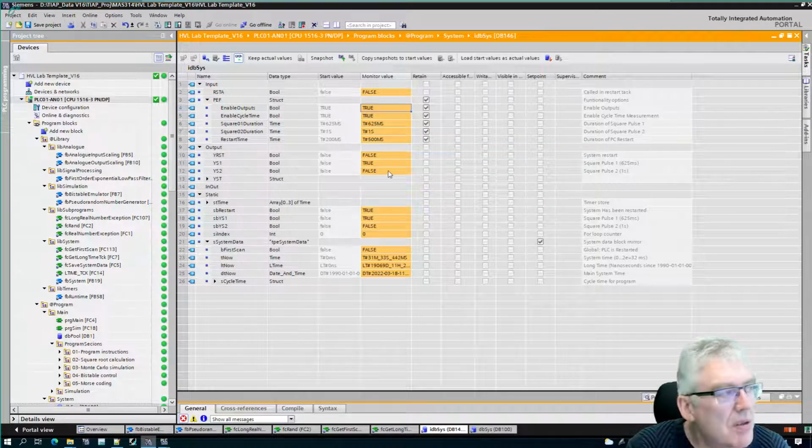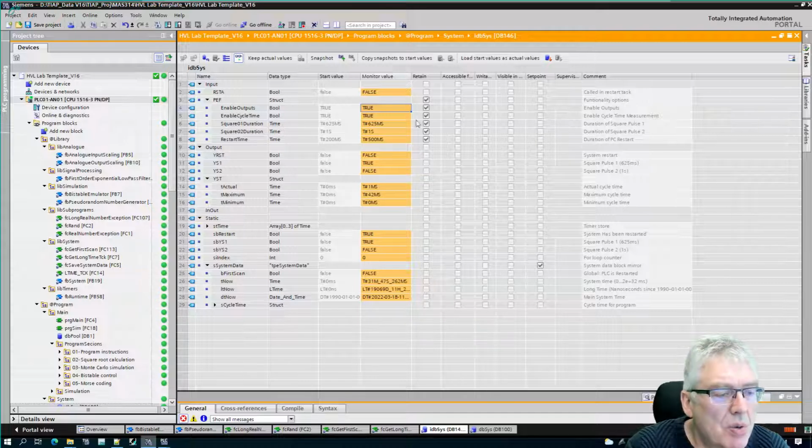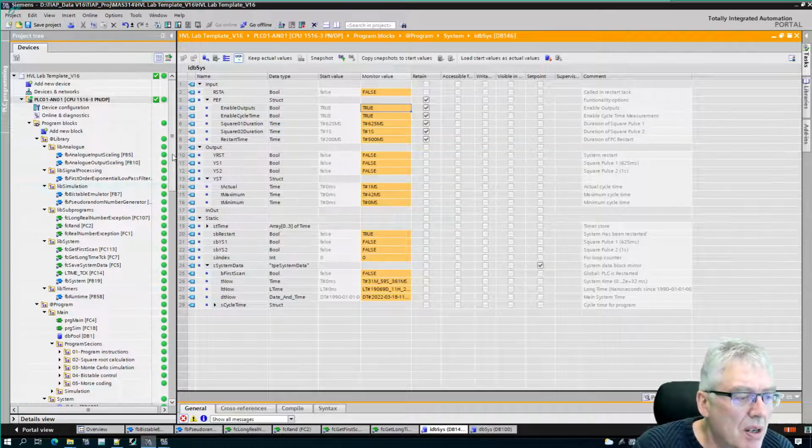It's just count, and every time you count, that's 1 second. You will need to make an edge test here. That was the cycle time. That's output here from this. So this is the system function. It doesn't do much, but it does enough. It provides some, let's say here, timing, first scan, and some square wave pulses that you could use.